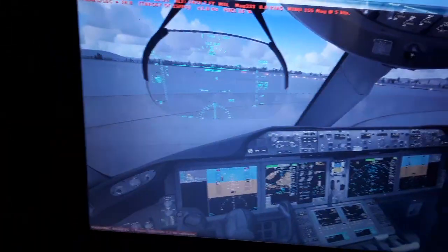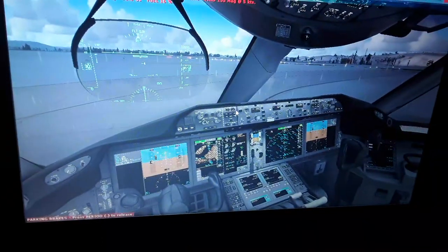So we will select a route from a departing airport to a destination, arrival airport and runway. So we're going to have departures and arrivals, SIDs, standard instrument departure waypoints and fixes, STARs, and arrival waypoints and fixes. And we're going to have the intermediate waypoints we have to fly through. You will see the purple magenta line of the flight plan we're going to create later.